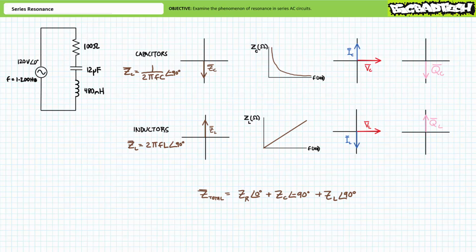It stands to conjecture there may be occasions in which there exist equal yet opposite amounts of capacitive and inductive contributions that entirely cancel one another out. This is known as a resonant condition, where the magnitude of ZC equals the magnitude of ZL. Again, the resonant condition happens only when the magnitude of capacitive impedance equals the magnitude of inductive impedance. Odd things happen at resonance, only some of which I'll explain today in this sanitized lecture.